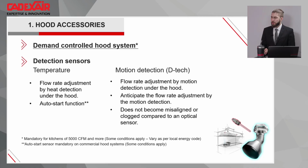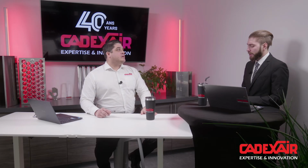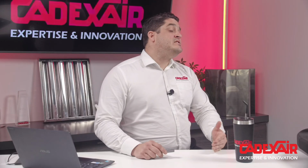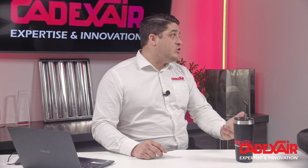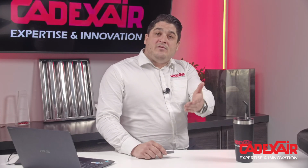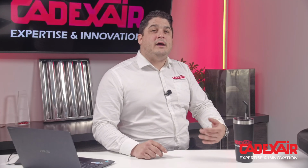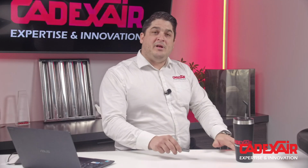Yeah, I heard that it was a standard or an obligation to have an auto start sensor, or is it just based on my need or if I have a smart system? No, since NFPA 96 2014, it's required to have an auto start function. So if we have the demand control, or what we call in our case the detect system, it will be built in.